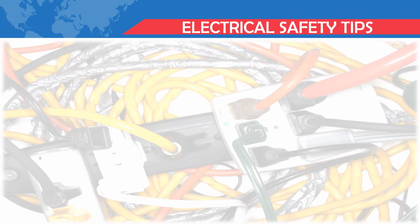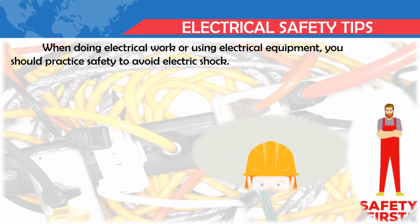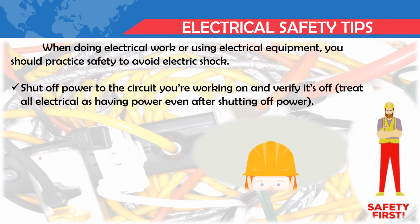Okay, next, electrical safety tips. When doing electrical work or using electrical equipment, you should practice safety to avoid electric shock. The following are the electrical safety tips. The first one is shut off power to the circuit you are working on and verify it's off. Treat all electrical as having power even after shutting off power.